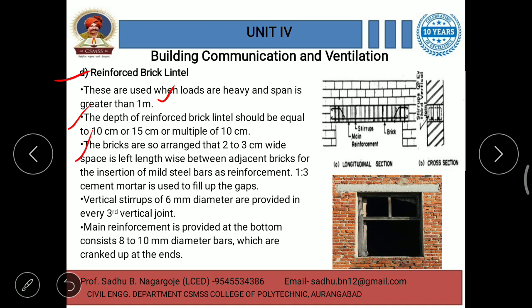The bricks are so arranged that a 2 to 3 centimeter wide space is left lengthwise between adjacent bricks for the insertion of mild steel bars as reinforcement. 1:3 cement mortar is used to fill up the gaps. Okay.